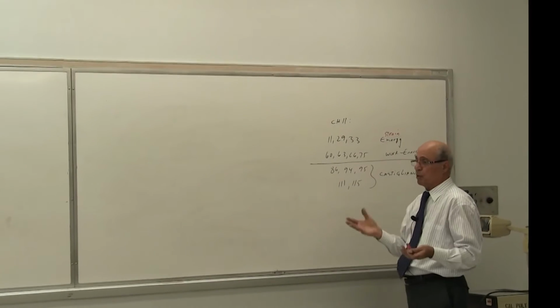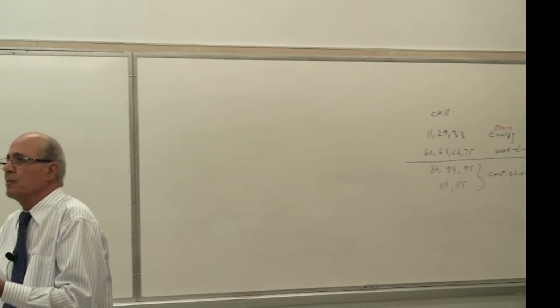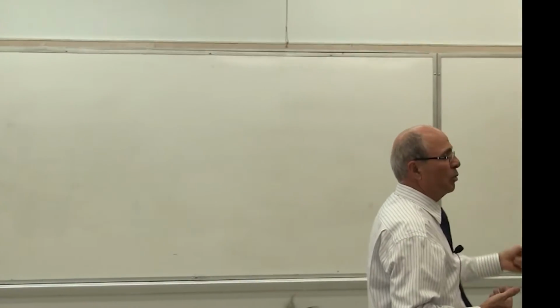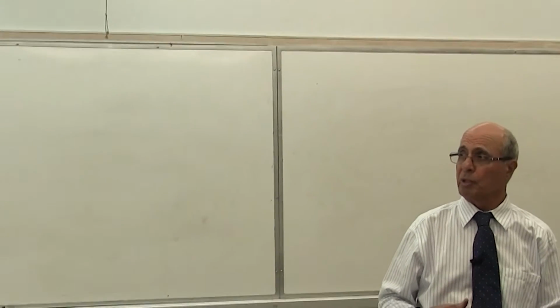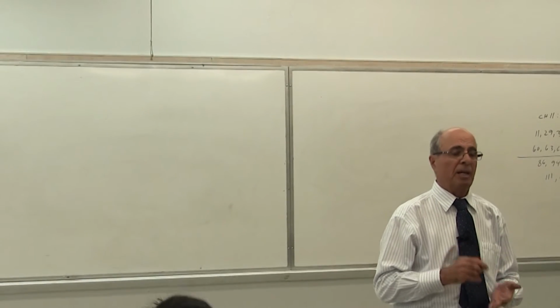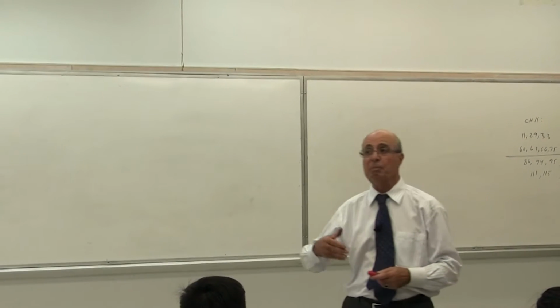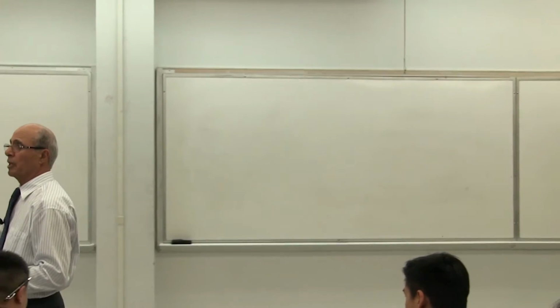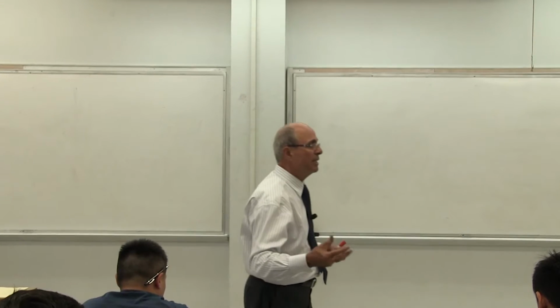Then, of course, after we do that, you will ask yourself, what's the purpose of this? Why do we calculate strain energy in a system? The next part of the homework will answer that question, because through this strain energy which is stored in the system, we are going to calculate the deformation or displacement. Notice we used many methods to calculate the deformation. We used Hooke's law to calculate the deformation for an axial member, which was delta equal to PL over EA.